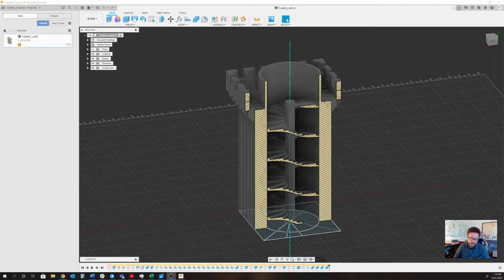In the previous tutorial, you were doing a lot of sketching. In this tutorial, you're going to be working a lot more with bodies. So it's essential that you remember to name objects after you create them. Be careful when you're using the different tools for cutting that you don't accidentally leave it on join, because two bodies will join together by default pretty easily. You can always go back in your history. You can see the history bar here, to better understand how that works. So without further ado, let's have a look at what I've set up for you.